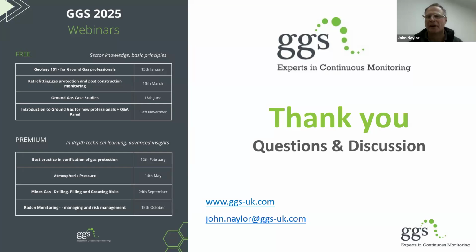Okay. Well, again, that's a good question, but it's a very complicated answer. It's very site specific. It depends on which VOCs you're dealing with and whether there's a mix of them. You've usually got to do this through a DQRA process, a risk assessment process, to figure out what concentration you would end up with in the building. You might even need to involve toxicologists depending on what you're dealing with.